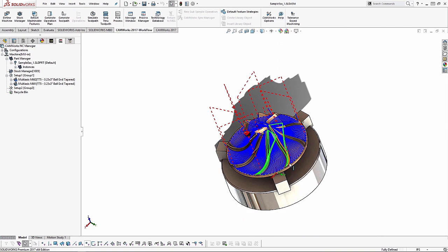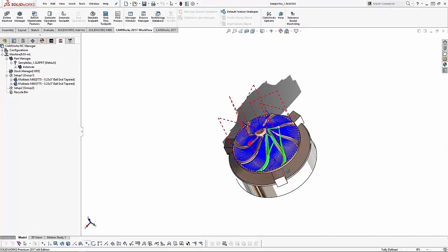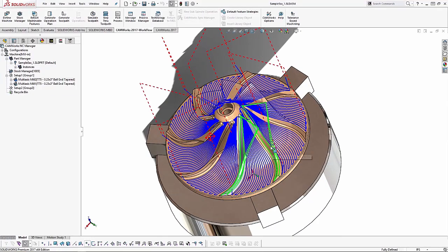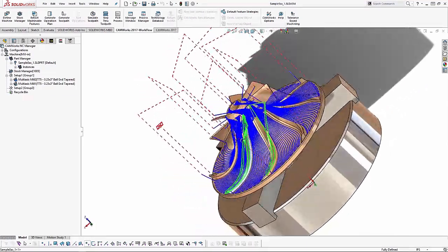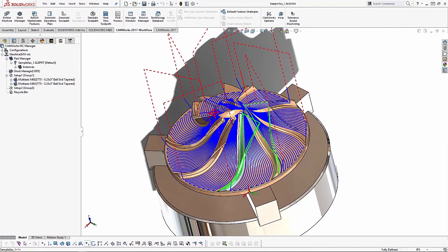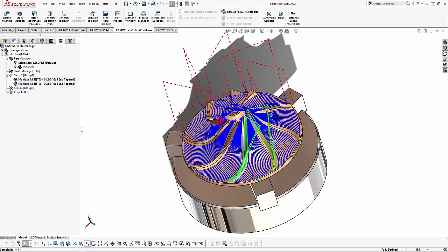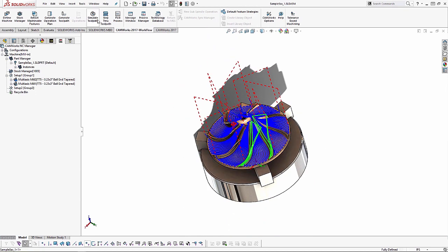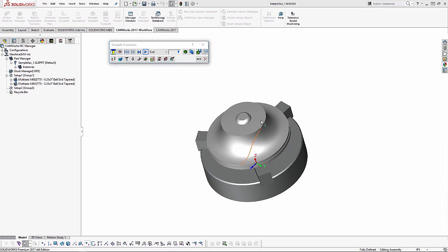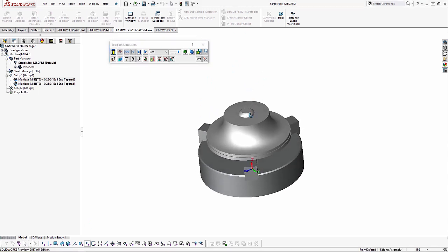This is going to be full 5-axis milling, pretty standard 5-axis part, some sort of impeller. We do have only the finished passes programmed on this, so the machine simulator is going to start warning that we're taking too deep of a cut, but we totally expect that. In the system simulation, you can see the stock shape looks like it came off a lathe. It's turned to size, and we're just doing the finished passes between the impeller blades.